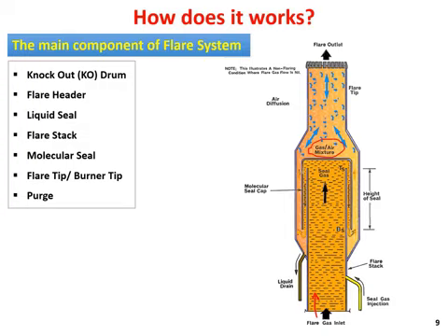We have also a liquid drain here. Why should we have such a drain? Because of the hydrocarbon gas that is coming out from the knockout drum, which is located somewhere here. Then we send the gas to the flare here.